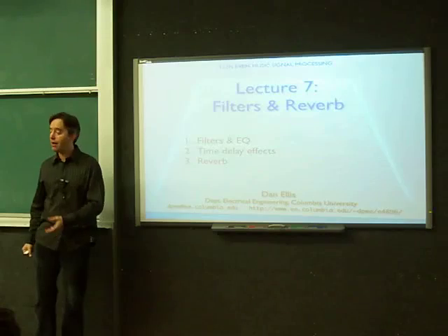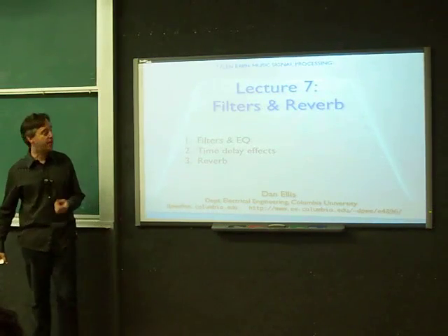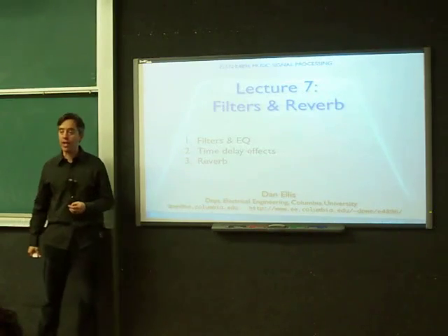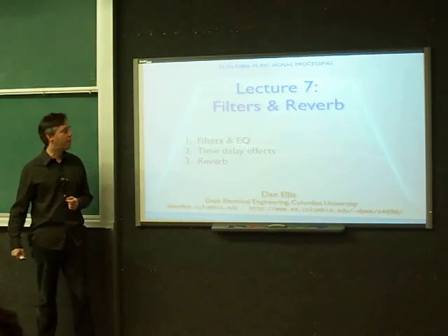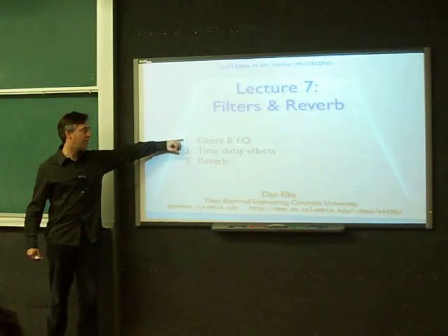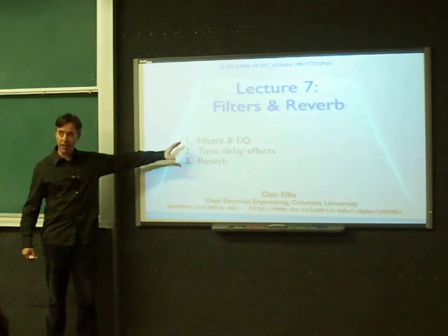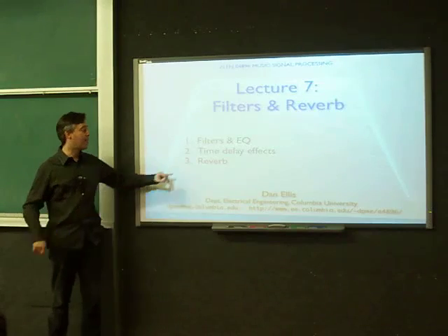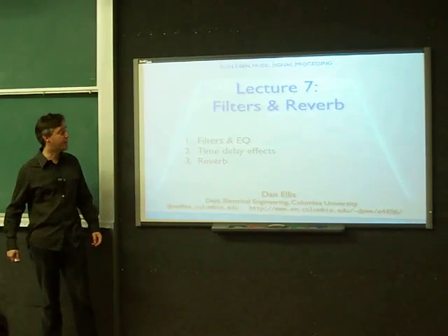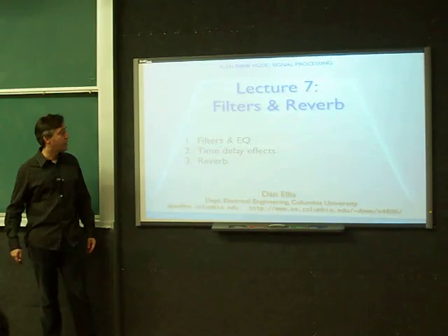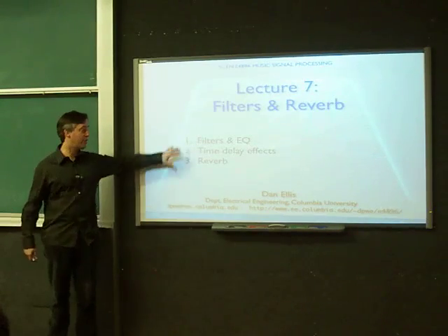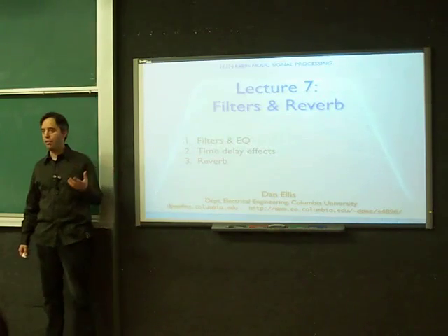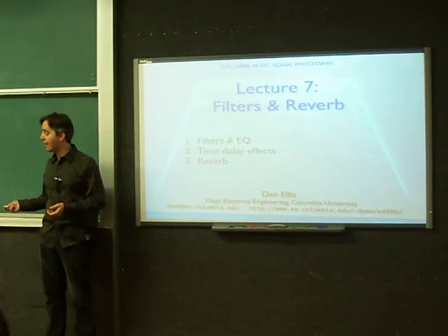So what we're talking about is taking the kinds of filters that we would study in signal processing in DSP and just applying them straight up to audio. But on the other hand, we're talking about a wide range of important and staple recording studio effects: equalization, time delay effects, including things like chorusing, and then reverb, which is in the same continuum, but a more complex thing, which is the simulation of room acoustics, and is extremely important in recording. So the goal today is to make a connection between these things that you can understand from an acoustic or perceptual point of view, and the actual underlying signal processing, which is a pretty direct link.